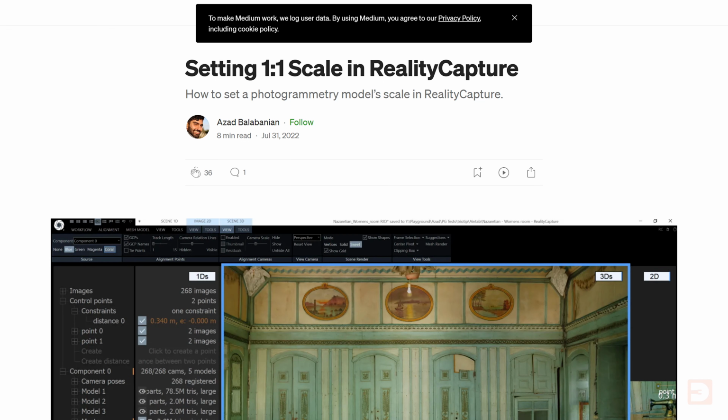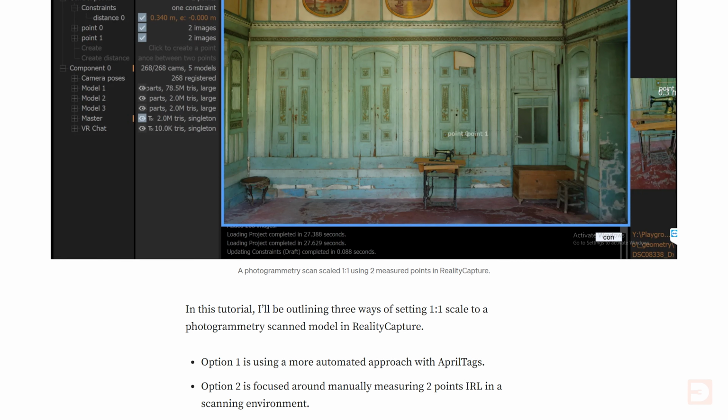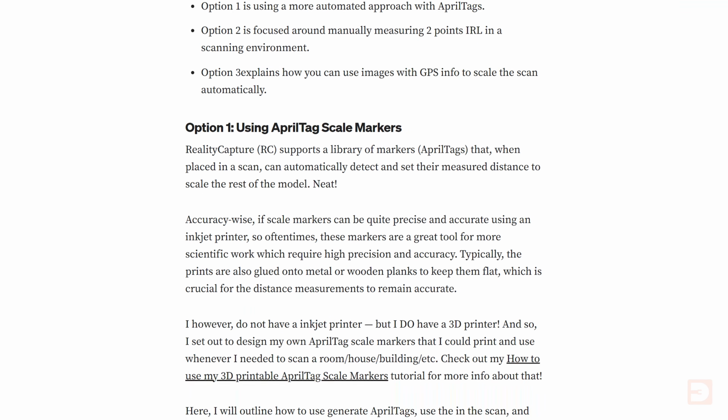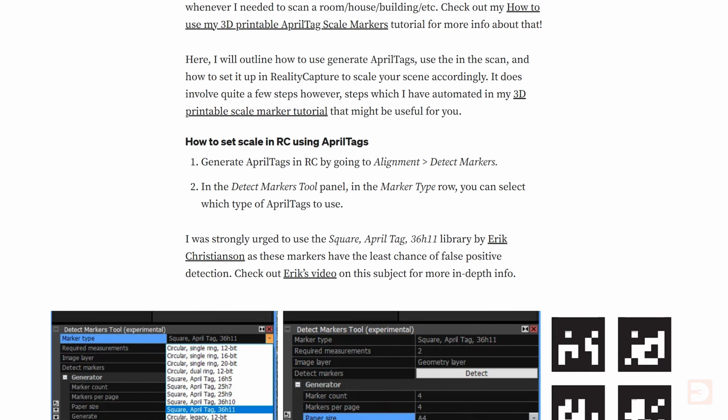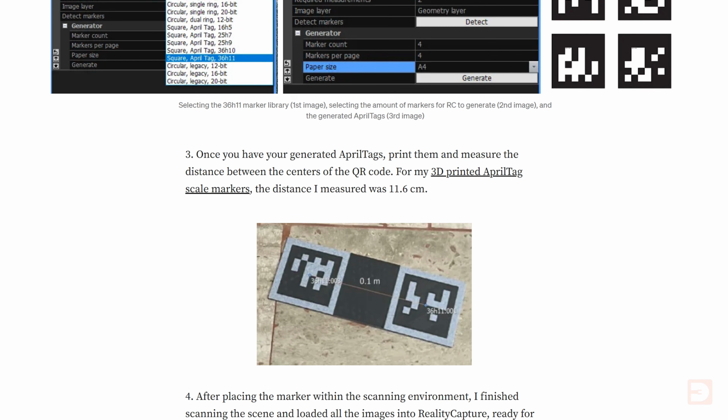Unlike other forms of 3D scanning, which can intrinsically know the scale of the thing that it's scanning, photogrammetry has no idea how big an object is. If it's important that your 3D scan is dimensionally accurate, placing a ruler or a simple object of known scale into the 3D scanning area can be really useful, because you can then scale up or down the resulting 3D model so that that object is the known size and the rest of your scan is going to scale relatively. With some software, including Reality Capture, you can create a scale bar and place it in the scanning area. The software recognizes it and understands the size, automatically scaling your entire scan accordingly.